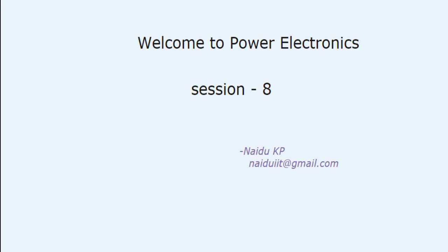We discussed voltage commutation circuit in the previous video and we discussed two issues in that circuit. One is commutation process is depending on the load current and the other one is the capacity or size of the main thyristor is depending on the commutation circuit. To avoid these two issues, we generally use current commutation circuit, nothing but class B commutation circuit. Now we will discuss class B commutation circuit.